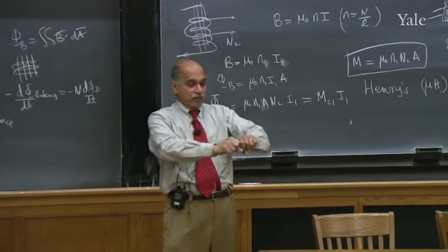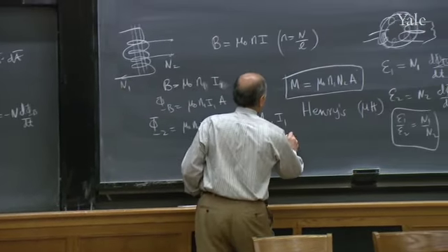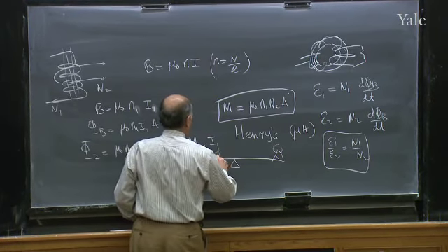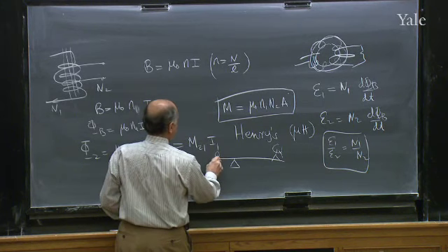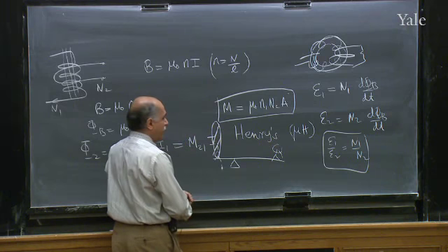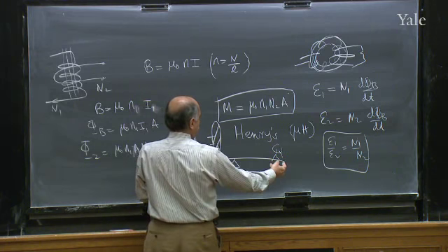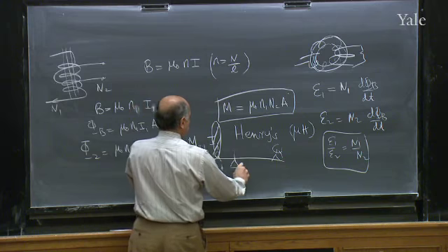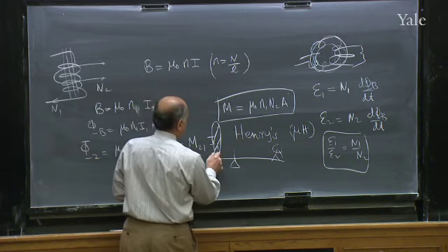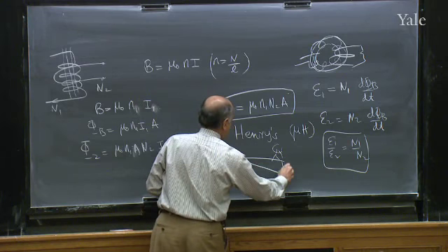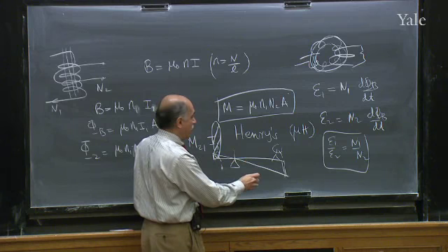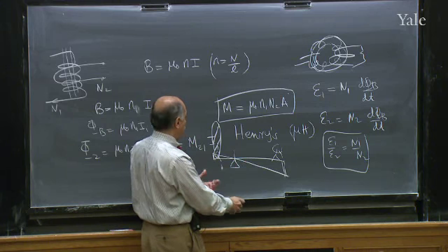It's like a lever. You have a long thing, and you're trying to lift some object here. I got it backwards now. So this is a huge object. It's a tiny object. You can balance them. By varying the distance, you can have a tiny guy lifting a big one in the inverse ratio of the distances. But you don't get any free mileage out of this, because if you look at the work done by similar triangles, this will have to move a lot, that'll have to move a little. So the work done is the same, but it doesn't mean it's useless, because this is the only way you can lift something very heavy.